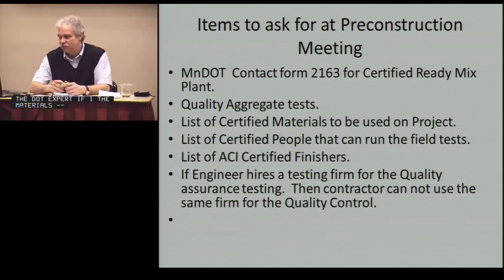What's different on this is there's going to be a list of certified people to run the field test, either the contractor's personnel, whether it's the flatwork contractor or the ready mix person. And for the first time, this specification asks for ACI certified finishers. There's a certification program with the American Concrete Institute that we instituted here, and we'll talk more about that later.